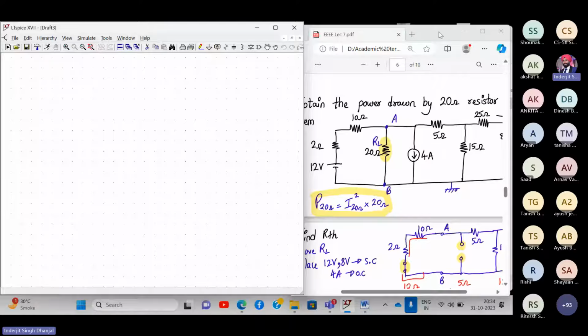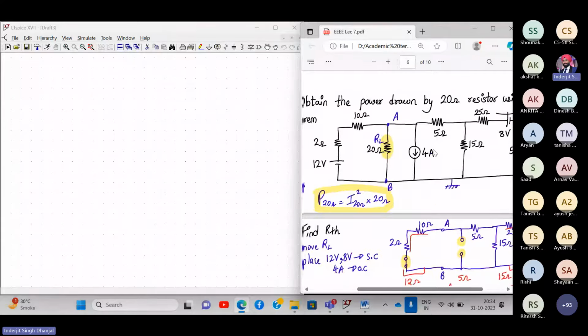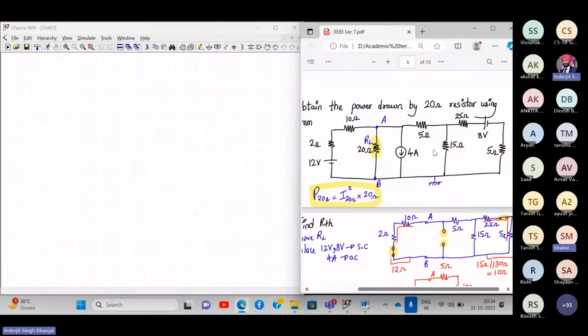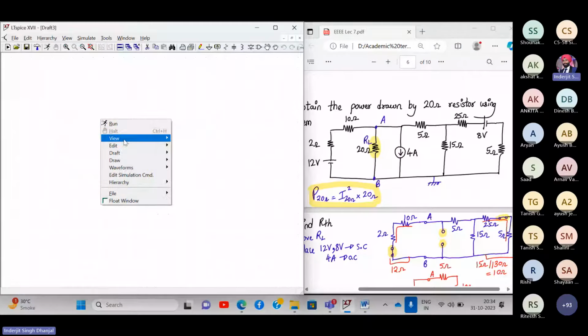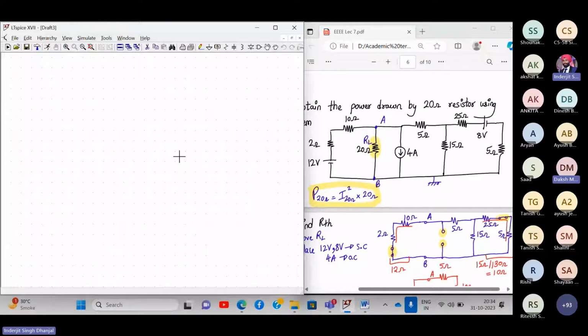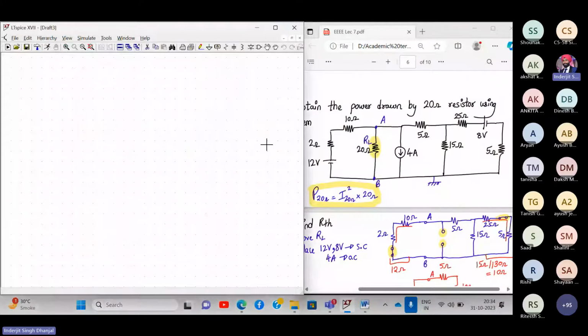Okay. So can we start now with this numerical? Could you repeat how you got the dots in the background? Yeah. Right click, view, show grid. Or you can press Control G. Yes, sir, also how to whiten the screen, that one I forgot. Yeah. Tools, color preference, schematic, selected atoms as background, and make everything 255, red, green, and blue. Okay, sir, thank you. Yeah, no problem.